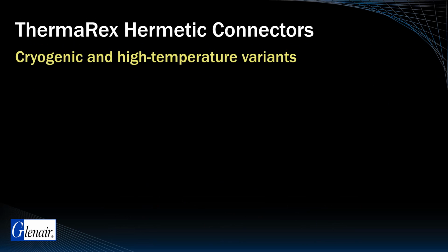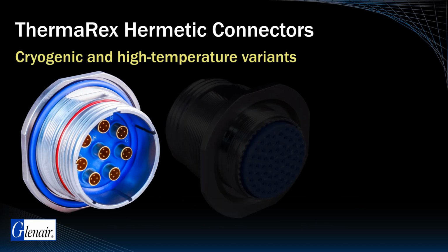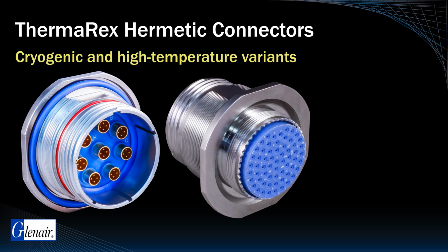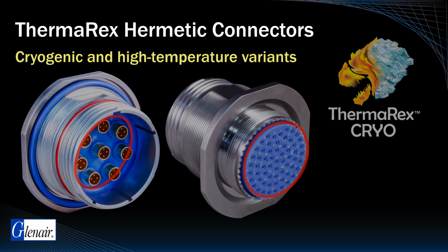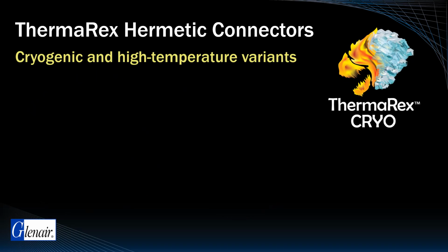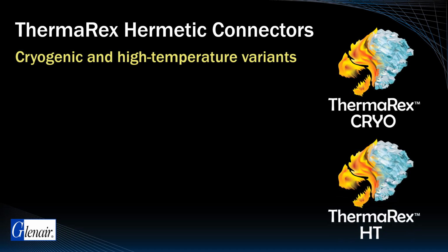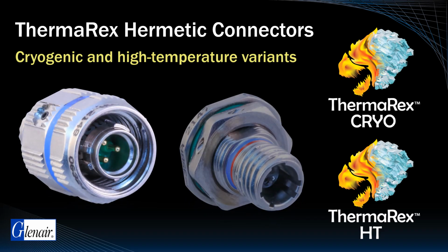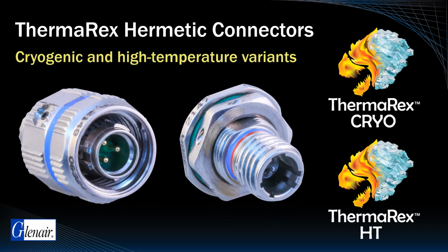All hermetic connectors, both glass-to-metal and encapsulant-to-metal seal, utilize standard interfacial and grommet seal component parts. For applications that require either cryogenic performance to -175 degrees Celsius or high temperature performance to 300 degrees Celsius, Glenair is able to supply Thermarex series connectors with temperature-tolerant interfacial seals and O-rings.